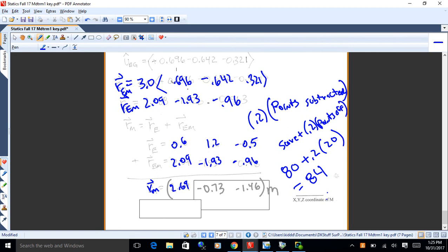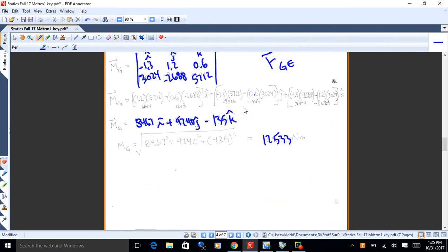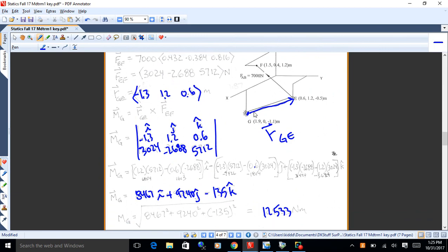The other thing is, on this one, I told you there will be moments, there will be dot products, there will be finding forces from position vectors. I flat out told you that. And so, to really prepare for this, you should have had that drilled. You should have known to do a moment, I take a position vector with a force vector and I cross them. Especially, I pointed that out about the moment problem because there seemed to be a lot of people having some problems with that, using the wrong type position vector generally. And you can't afford to be scratching your head about this stuff.